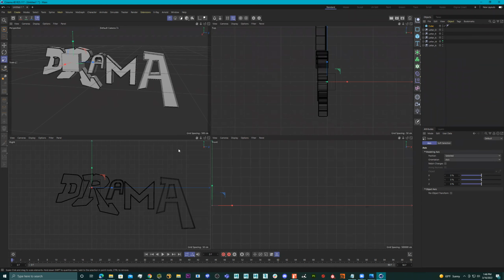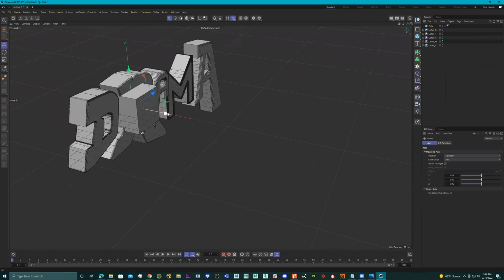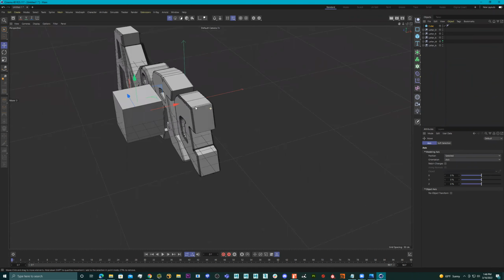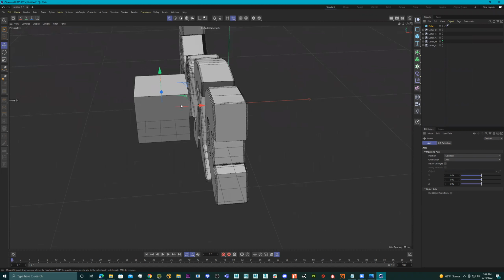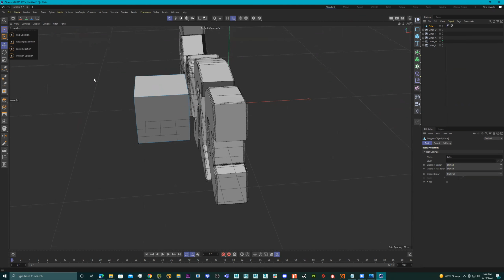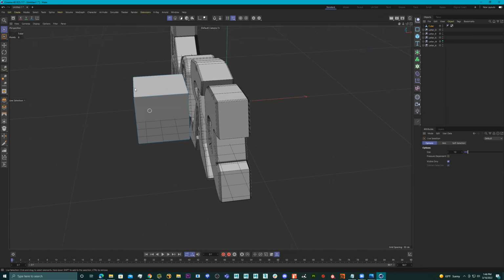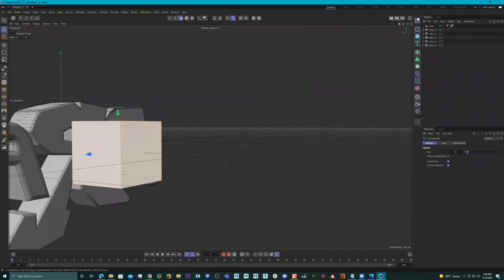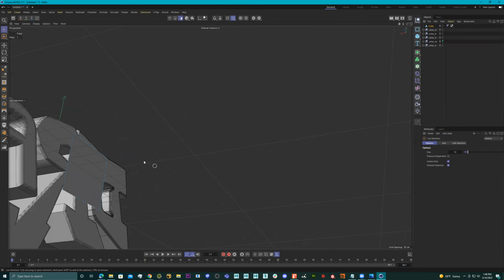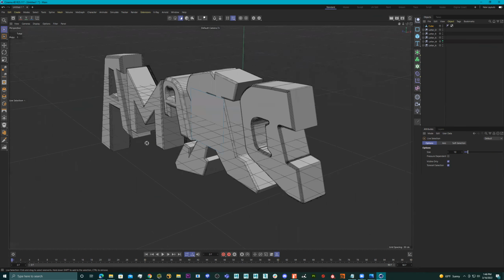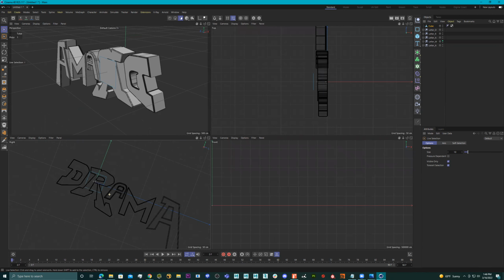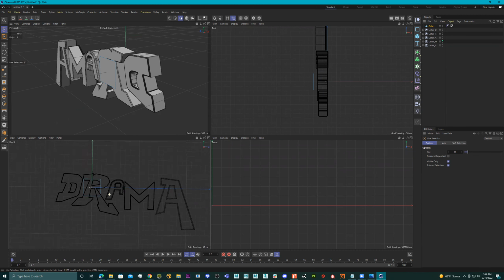All right. I'm just gonna do this just because, and press C to make it editable. Go ahead, press 9 and go to my faces and just delete every face but this front face. Oh, didn't mean to rotate that. I wish I could lock that. If anyone knows how to lock it, let me know.